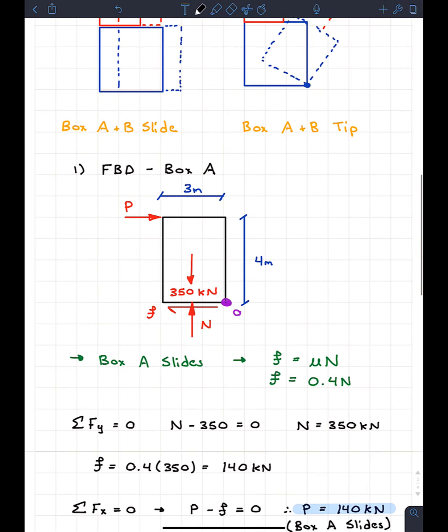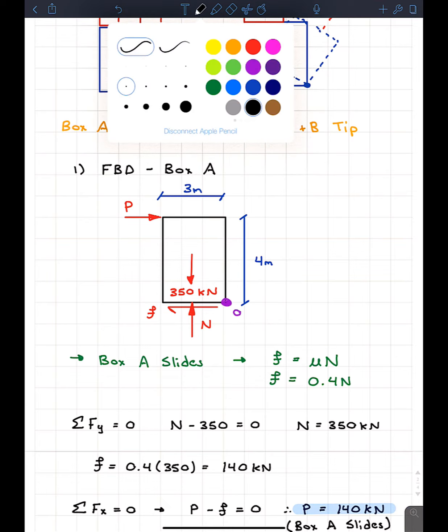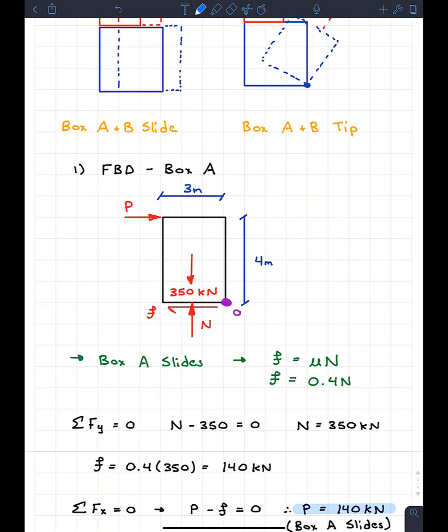And then a lot of people say, okay, well, we got a normal force acting halfway across, but we actually don't. This is one of those tricks that can get students, because when something starts to tip, I'll draw it here. Let's pretend that this blue line right here is the ground. When something starts to tip, the box is going to come slightly off the ground, ever so slightly off the ground like this. So the normal force actually transfers to the end.